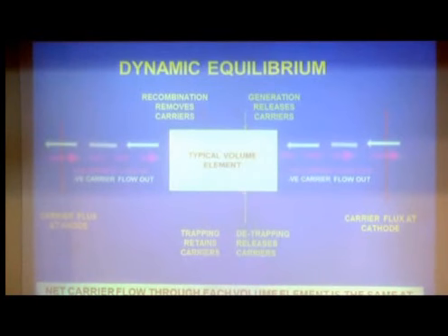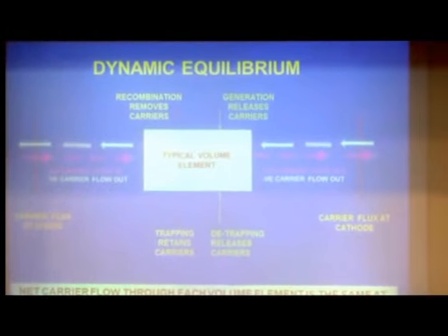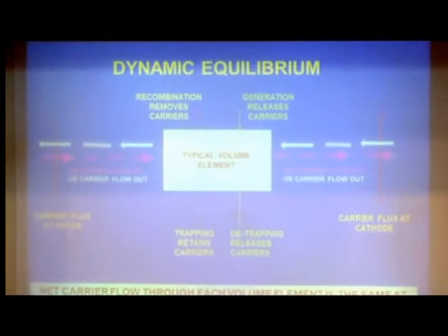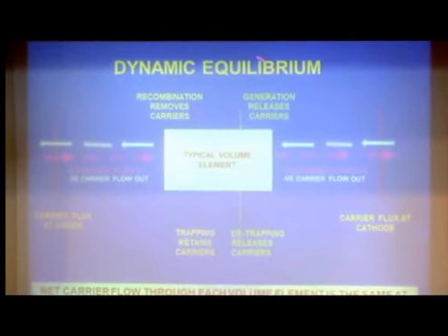There's one further point about this dynamic equilibrium. Very often we have traps at different energy levels, and it's assumed automatically, I think, that the probability of finding a charge in one level or another obeys either Boltzmann statistics or Fermi statistics. That presumes that the charge flow into that level equals the charge flow out of that level. It's called detailed balance, but it's not necessary to give a dynamic equilibrium.